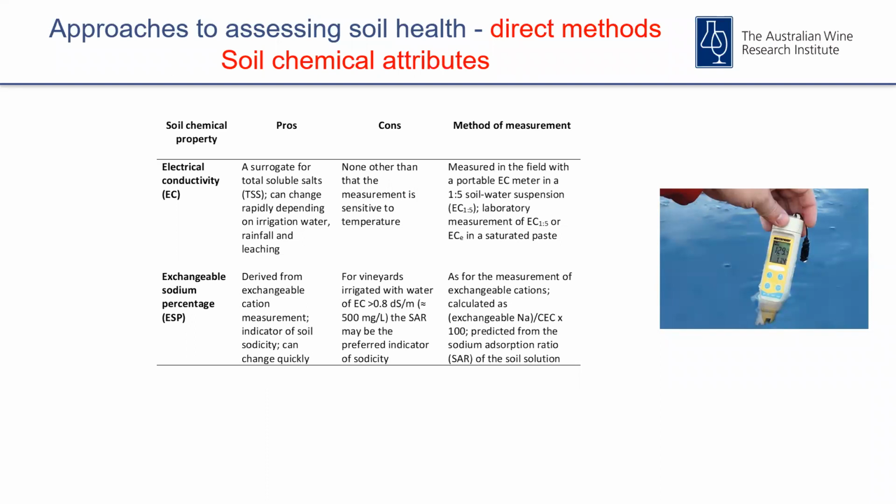And understanding the exchangeable sodium percentage is really important too, in knowing whether our soils might be exhibiting some sodicity problems. It's derived from exchangeable cation measurements, and that's a good indicator, like I said, of soil sodicity.